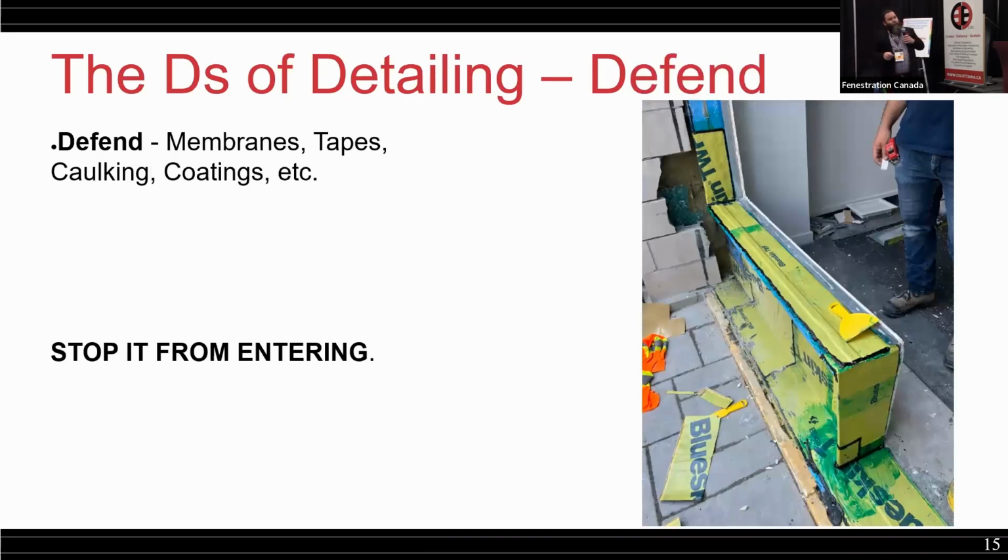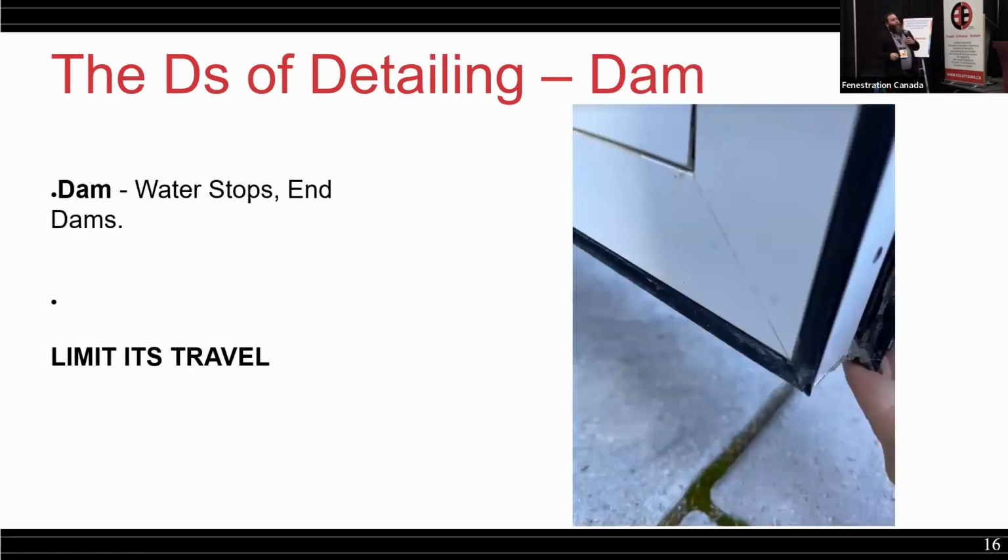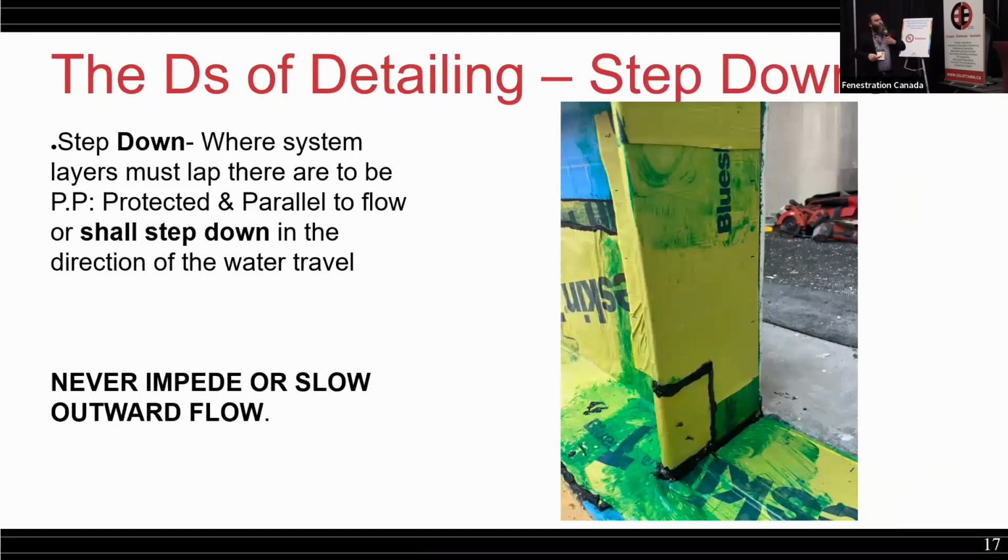Defend it. So this one's a bit full on. I thought this was a funny detail and a great photo of a funny detail, so I've included it. But yeah, that's a lot of blue skin, but the idea is there, right? Ultimately, if you've got a membrane of tape, caulking, coating, you're going to be defending once the water is in position. Dams, water stops, limits the travel.